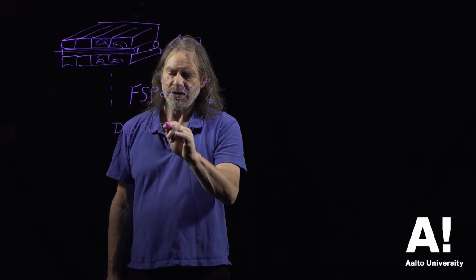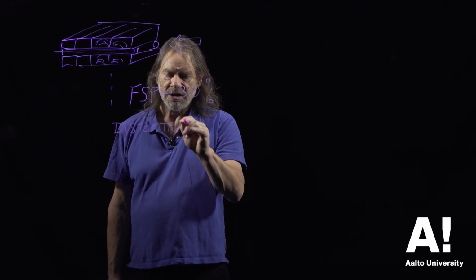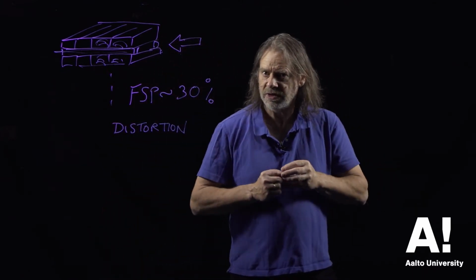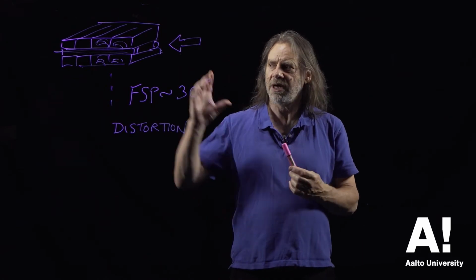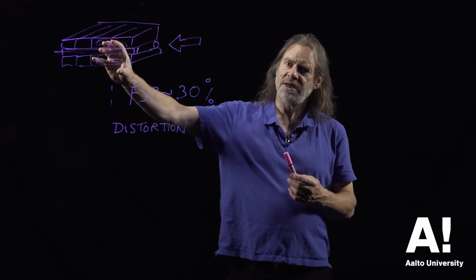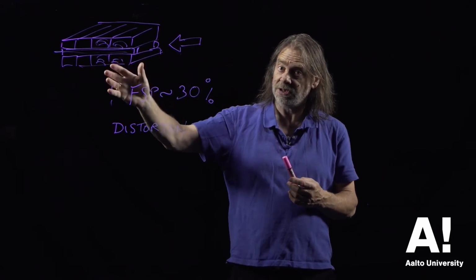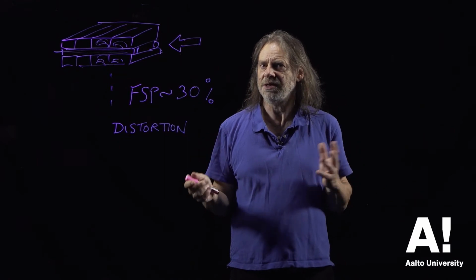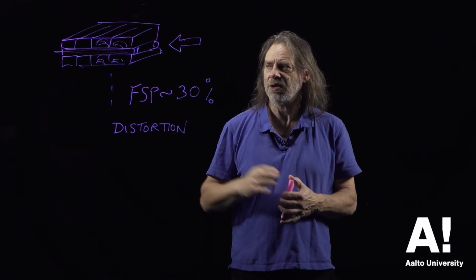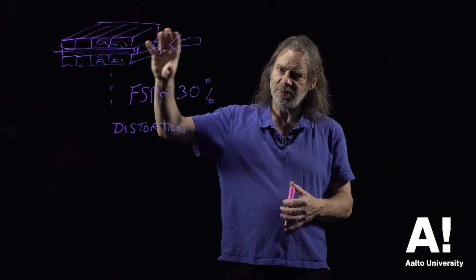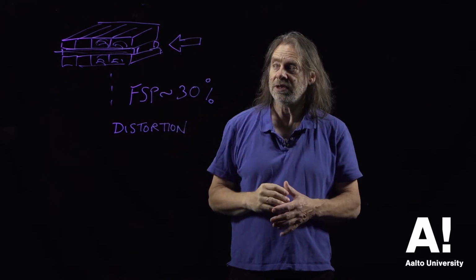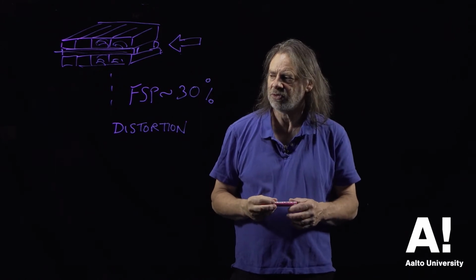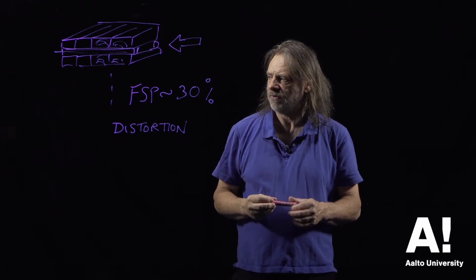And we can avoid, or at least minimize distortion if, first of all, we follow the kiln schedule very carefully, and we make sure that all the wood that's stacked in the kiln has the same dimensions, is from the same species, and each piece is as similar to every other piece as is possible, because then that schedule we can apply to that particular type of wood. If we put in mixed dimensions or mixed species, we're just going to have trouble. So we have to be extremely careful about that.